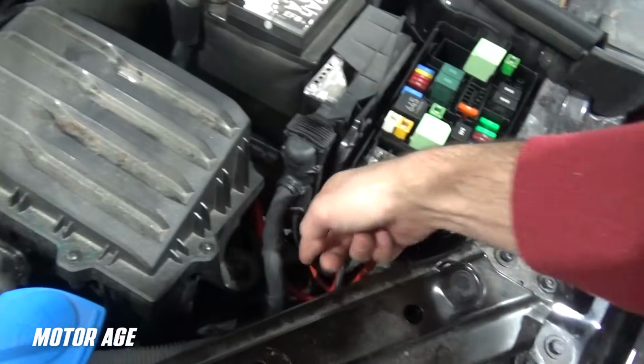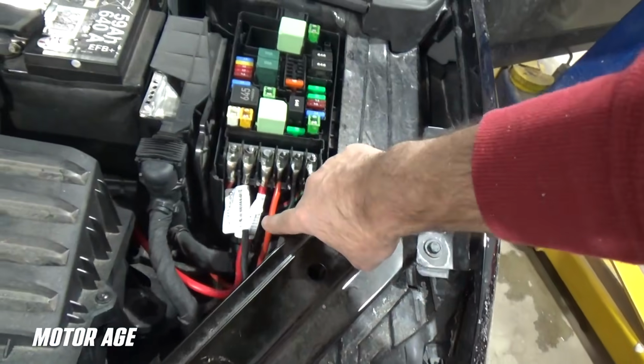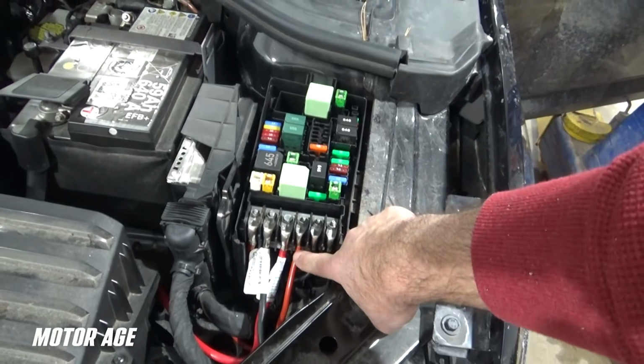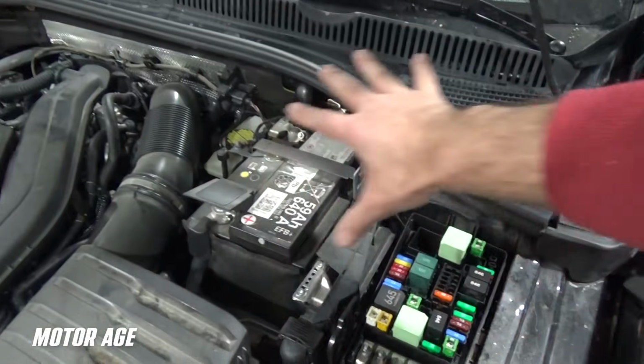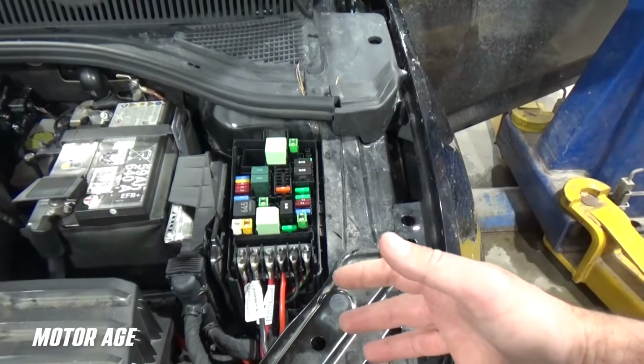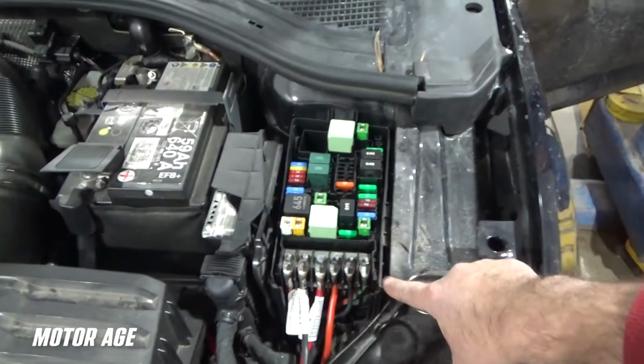Without taking anything apart, we can strategize by leveraging the amp clamps along with the scope to give us graphed out data over time, and sometimes this time frame could be several hours to even overnight. And we all know with intermittent problems, especially with some of these European vehicles, chasing parasitic drains can be somewhat of a nightmare. So again, we're going to leverage our scope. We're going to put 1 amp probe here to prove the current flow is present. And we are going to leverage several amp clamps around these remaining cables to find out which one houses the draw. And the idea is divide and conquer. Rather than tackling the whole vehicle in its entirety, we're breaking the electrical system up into subcategories to find out which of these 5 portions houses the drain.